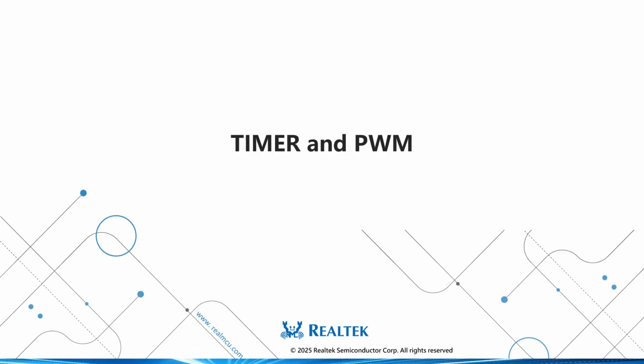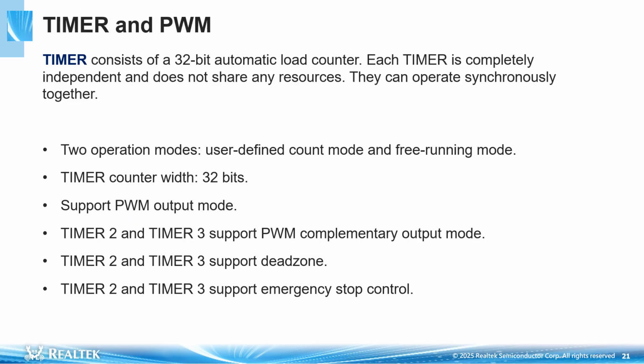Next, we will introduce timer and PWM. The timer consists of a 32-bit automatic load counter. Each timer is completely independent and does not share any resources. They can operate synchronously together.